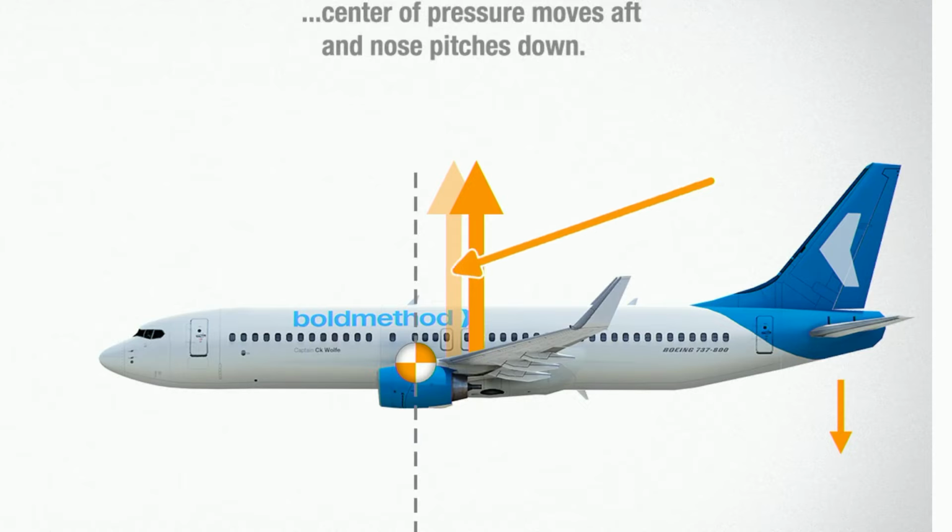If this lift suddenly starts to jump back, we have a different arm between the center of gravity and the center of pressure. Now let's look at those. If we look at the original arm, it's fairly short, and the new arm is longer. Okay, so basic leverage, right? With basic leverage, as we increase the length of the arm, you end up with more torque, right?